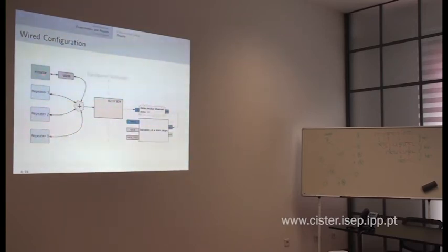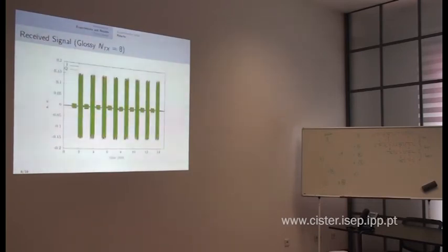In order to do that, the information that we put in the payload of the packet that this node is going to transmit is known. Then, in software, we look at the result of what we receive here and compare. And then we will do the statistics of how many errors we get.